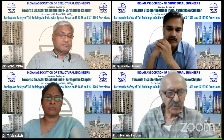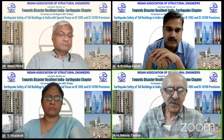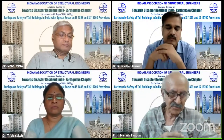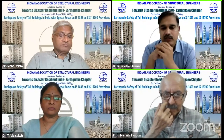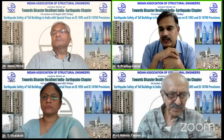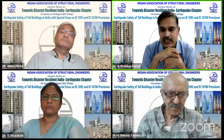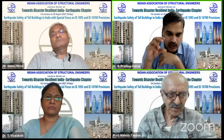Is there any parameter specifying the allowable acceleration or velocity values? The zone factor is that one only. Whatever zone factor is given is for the maximum considered earthquake, and that is double of the design earthquake. That's why it is used as Z/2. And this part also I will elaborate in the next lecture.